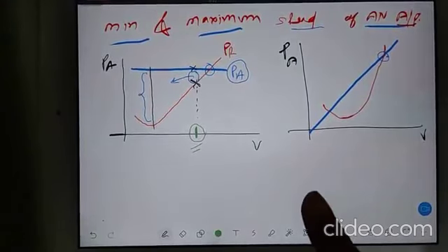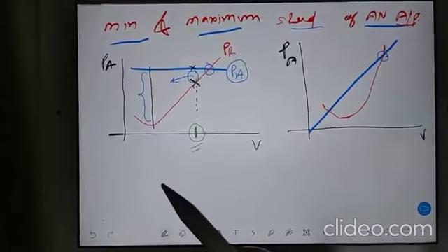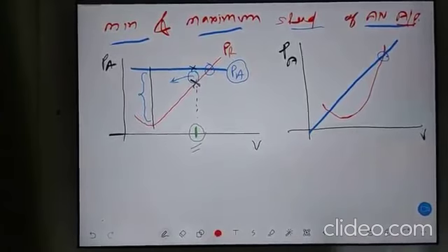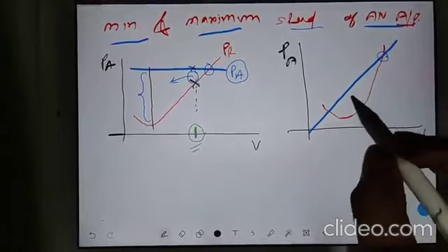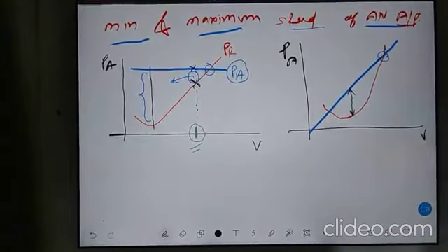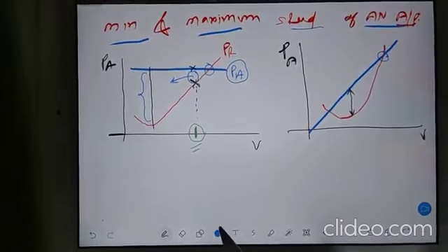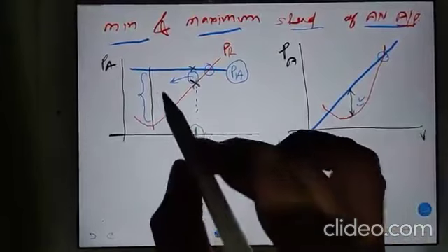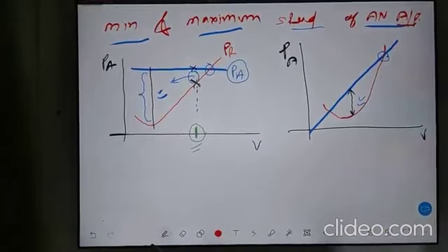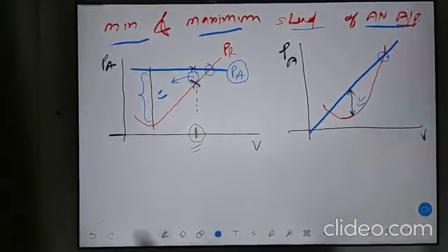There are so many ways to use this excess power. You can use it for climbing. You can use excess power for running extra devices. There are so many things, because that is power. That power you can use for any purpose. But if you see the maximum gap in this second condition, it is only this much. So you can clearly see that in this gap and this gap, power available is more. In which condition is power available more? In propeller condition.